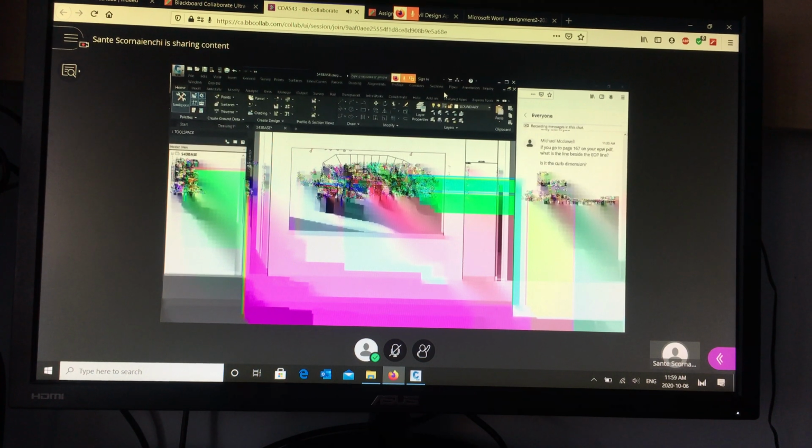So we don't want to see these frames. We put them on the layer called viewport. You'll always see them in the drawing, but when you go to plot, if you do a preview, you won't see the frames because they're on a no plot layer. And that's the look you should have. You don't want to see the frame.